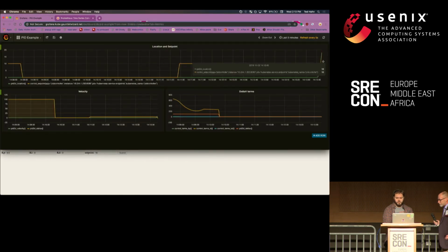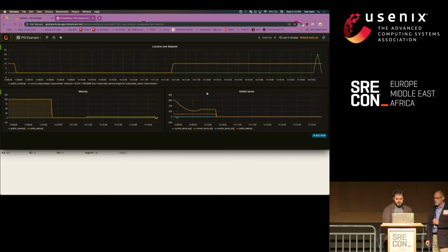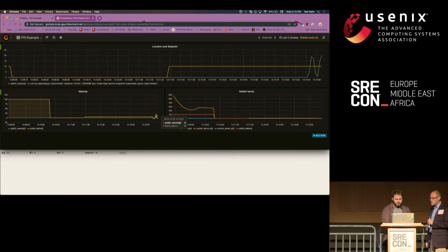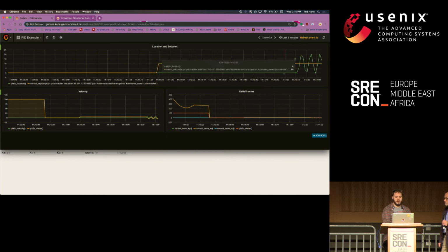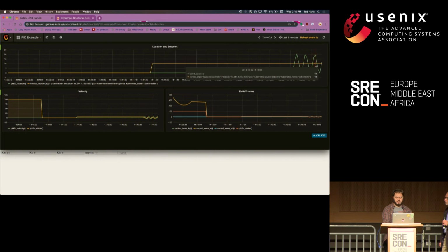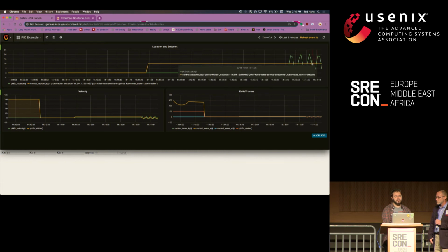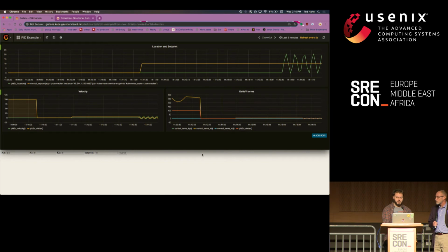Okay, so now we can see that the delta V has gone up, and our purely proportional controller moves our location up and overshoots, and moves our location up and overshoots. And it will continue to oscillate at roughly the same point around our set point forever. This is what a purely proportional controller will do. It will get there, and then it will overshoot.